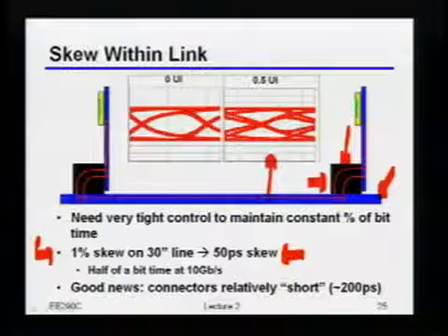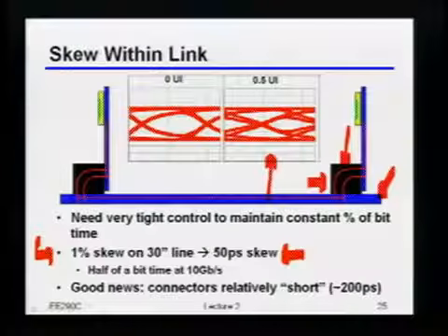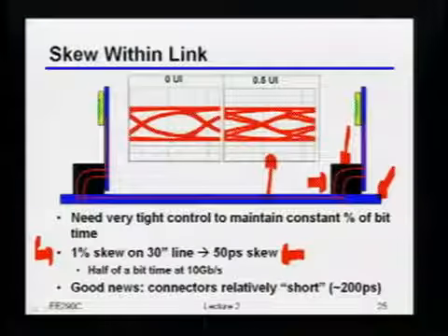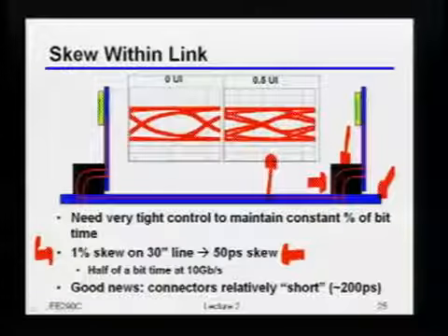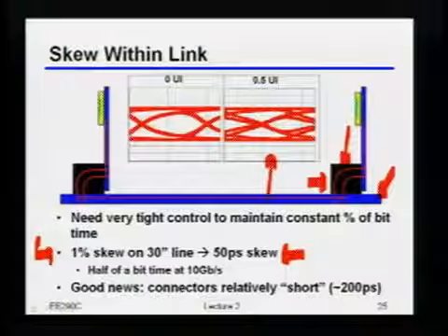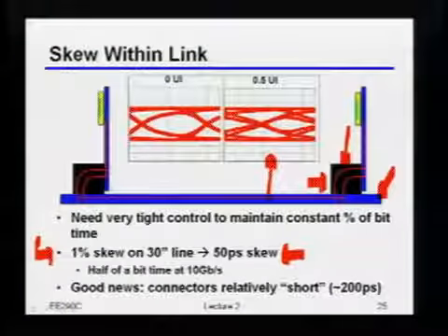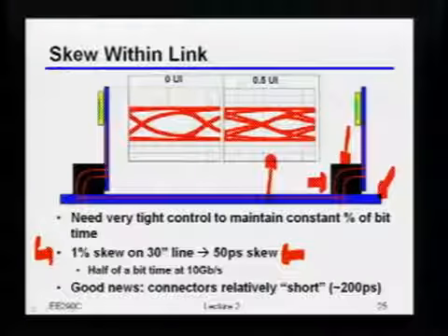So that's certainly something that from a, let's say, a link budgeting standpoint, and in fact, even from a link modeling standpoint, people will actually go in, they'll take their VNAs, vector network analyzers, they'll plug them into these backplanes, they'll put that in a temperature control chamber, they'll actually change the humidity, they'll measure it on different times of day or phases of the moon or whatever, right? They'll really check how much variation do you actually see in that particular channel. Does that make sense? Or?